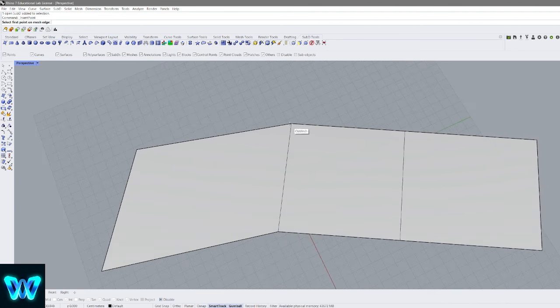So one important thing is that you have your OSnap enabled, which you can click here and just enable. So it will snap to the vertices, and to your edges, to the middle points, etc. The way I do it is I always keep it disabled because I like the freedom of putting things wherever I want, and then I just press Alt to snap it, because what Alt does, it just automatically enables OSnap. You see it here. But let's disable it now, just so we can work better.